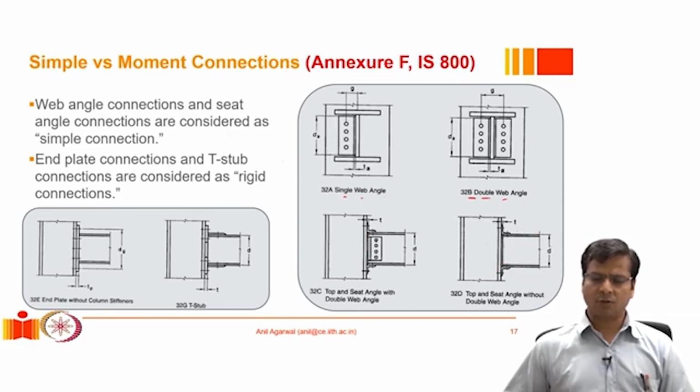In this case as well, you might realize that it is contradicting what I had said earlier. I had said that the connectors should not be towards or very close to the flanges, because if the connectors are placed close to the flanges, they may resist moment as well. But we are classifying these connections as simple connections, even though we are putting the connectors close to the beam flange, like here and here. Okay, so I'll give you a moment to think about it.